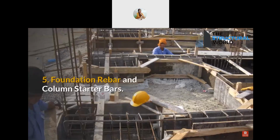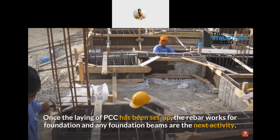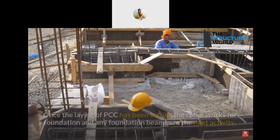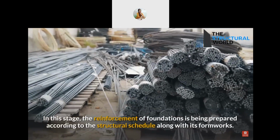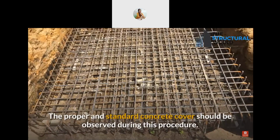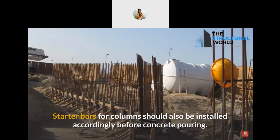5. Foundation rebar and column starter bars. Once the laying of PCC has been set up, the rebar works for foundation and any foundation beams are the next activity. In this stage, the reinforcement of foundations is prepared according to the structural schedule along with its formworks. The proper and standard concrete cover should be observed during this procedure. Starter bars for columns should also be installed accordingly before concrete pouring.